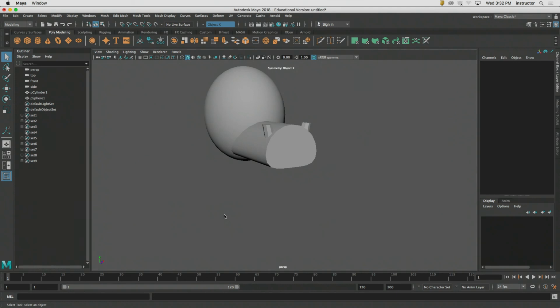One thing on the sub-D note, Mudbox does not understand subdivision surfaces, okay? Fundamentally, it doesn't understand it. So we can't use any sort of sub-D surface on our meshes in the game art pipeline. Which is both a good and a bad thing.